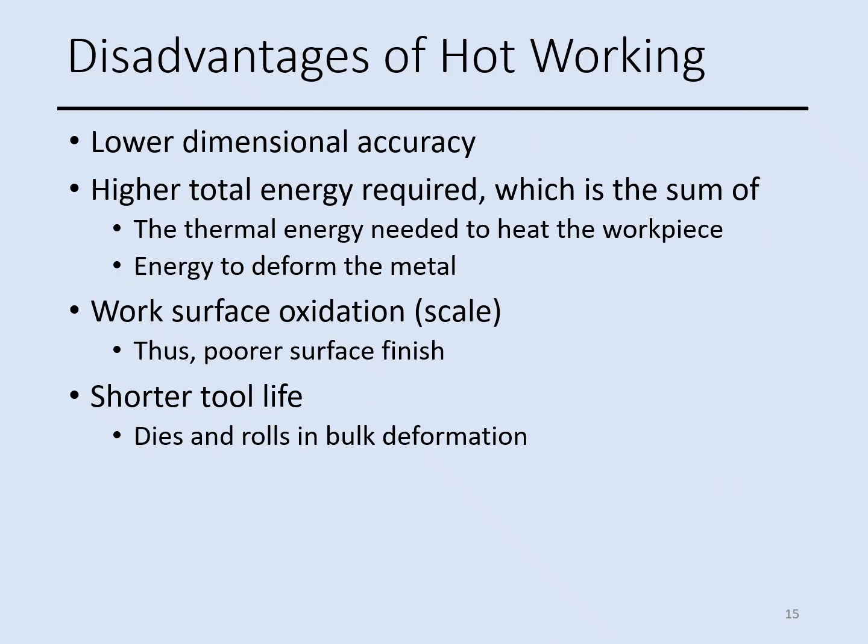There are some disadvantages for the hot working processes. There is lower dimensional accuracy; the accuracy goes down with this process. You need more total energy, because you need to heat up the part. Thermal energy is needed.